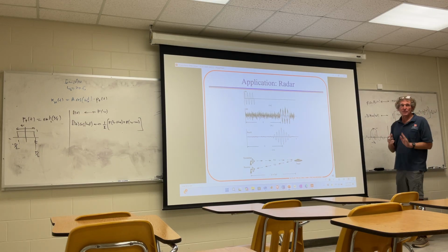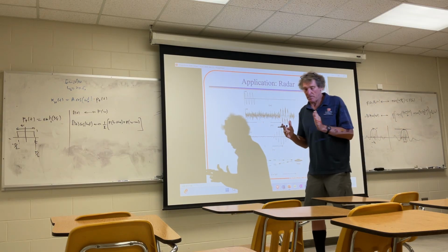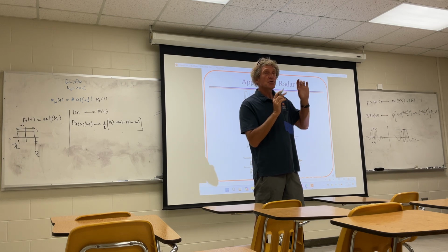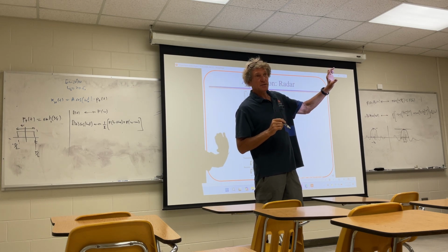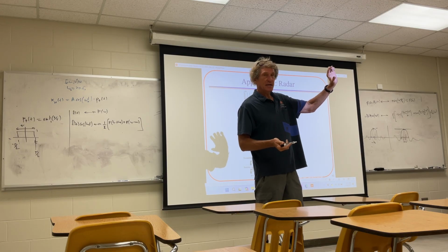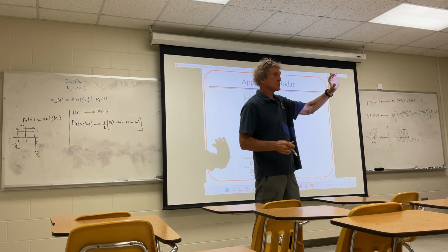Basically, you're going to have a spike. And that means the frequency that you're actually transmitting, the majority of the power, is over a very narrow range of frequencies. So your antenna that is designed to transmit at, say, 6 gigahertz or 10 gigahertz, it will launch all that. Even though there's a slight variation in the actual frequency components, it'll launch it.